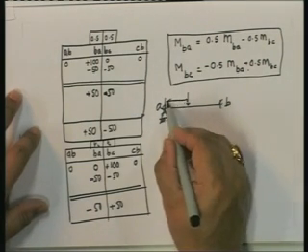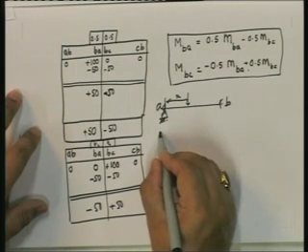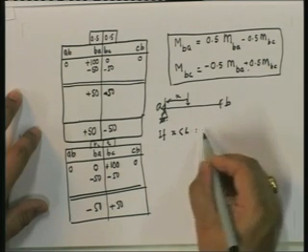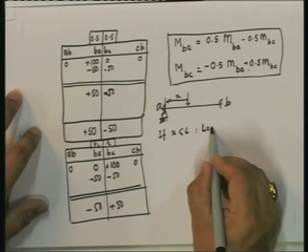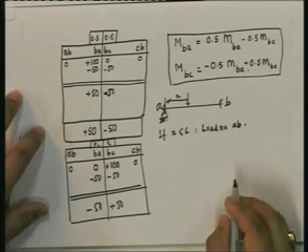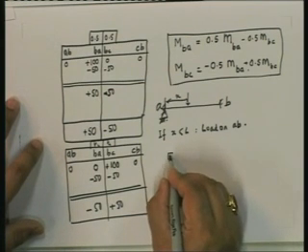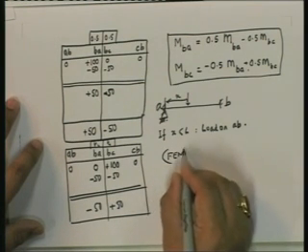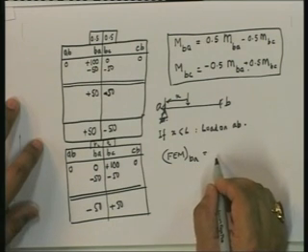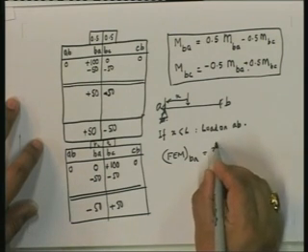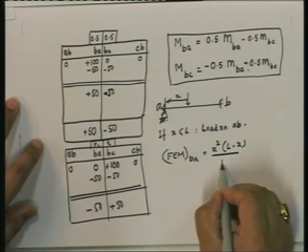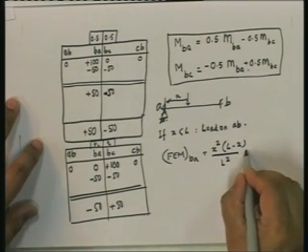If the load is at x, so if x is less than L, that means the load is on AB, then the fixed end moment at BA is equal to, think about it, it's going to be x squared (L minus x) upon L squared.